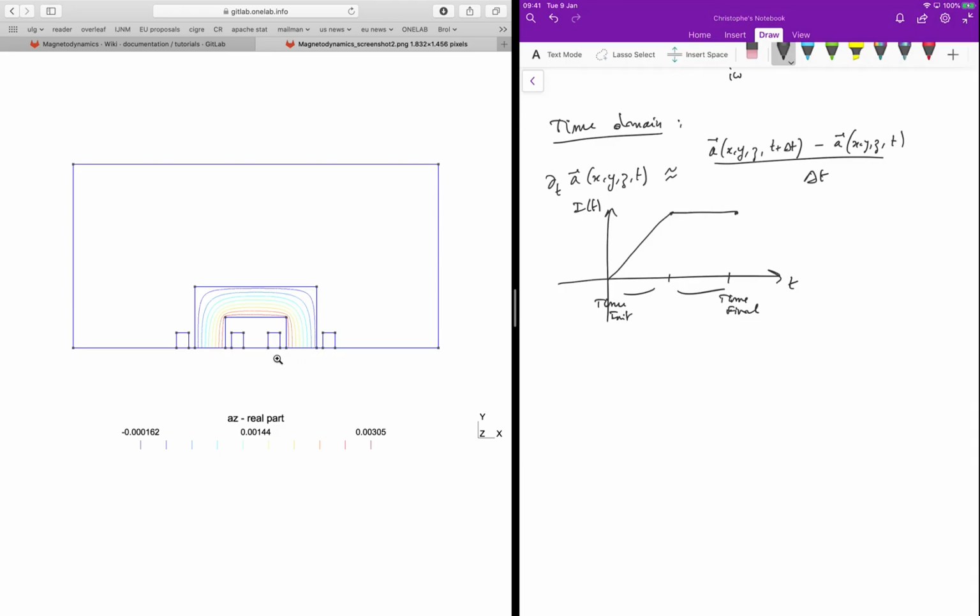And so, if we wanted to do a very simple test with no load, for example, we could do it without circuits. We could impose the voltage or the current over here, and then we could basically measure voltage over here without current. But if we want to be realistic, what I would really want to do is to derive what is called the exterior characteristic of the transformer.